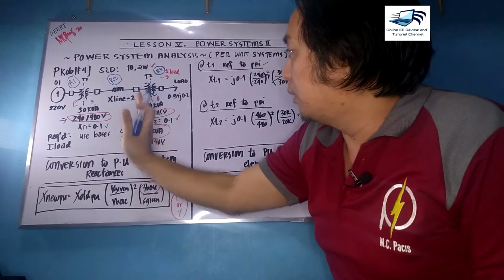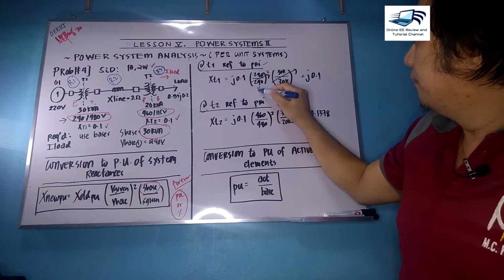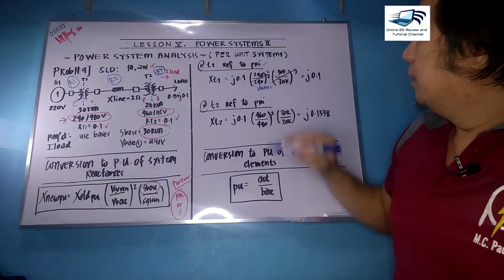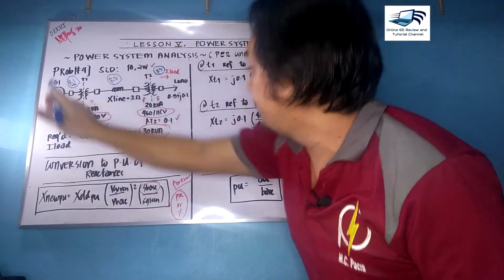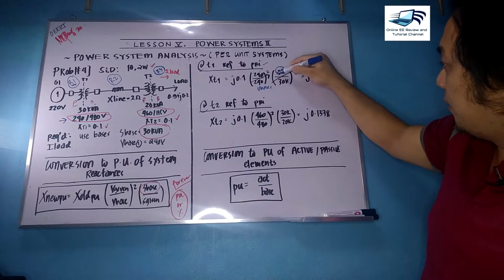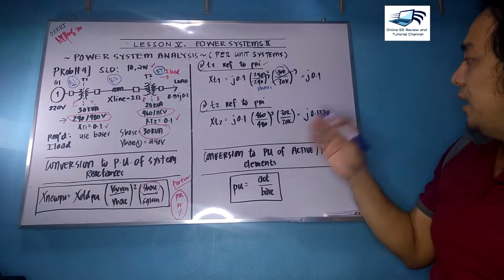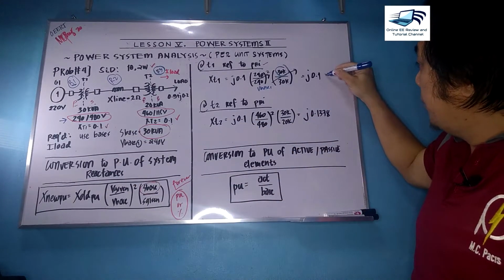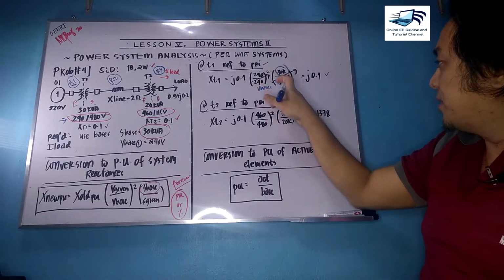If you can still recall, V base number 1 is 240 as well, because the transformer given is on region number 1. And then the base value is 30K, that's the S base, and then 30K for the S given. As you can see here, you can have 0.1 as well, simply because V given and V base, and S base and S given is the same.